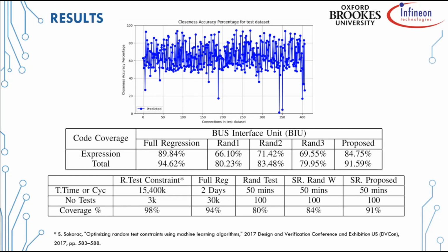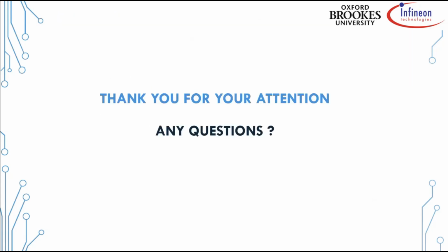I think that was the question here, and it's because normally the ranking tools do the whole SOC rather than target the particular change that you've made. So they target the particular change that you've made. If you say I've changed this block, tell me all the main blocks that are connected to it, then you can have higher confidence with much reduced performance. Yes, it's for the specific thing rather than the whole coverage.